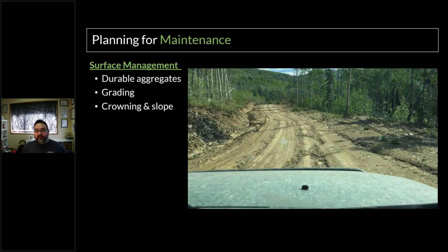I was up north, and a highway supervisor told me that aggregates are no good for road surfacing, and the example was, look at the road surfaces, they're all silt, and the aggregate's all on the side, so you don't need aggregate for your road surfacing. Well, if you have that, you're going to get what you have in the picture there. The problem with that particular road he was pointing at was not that it had aggregate in it. The gradation wasn't right. So you need the aggregate to create the base of your surfacing, and the fines, that proper gradation will lock that all together.